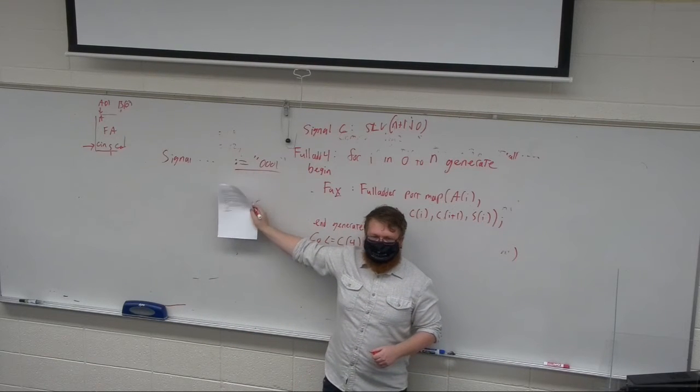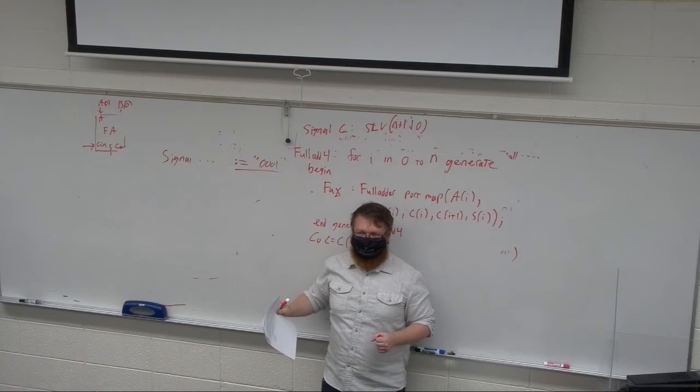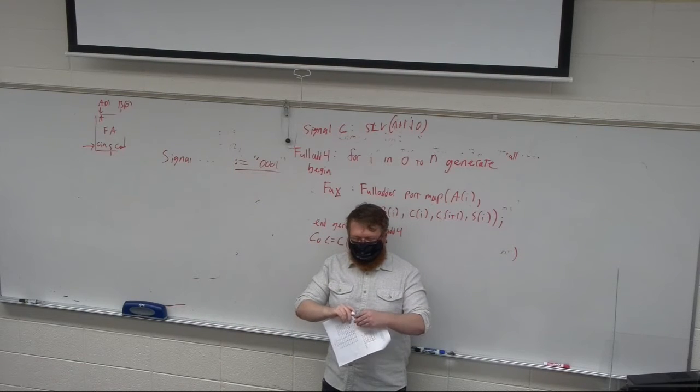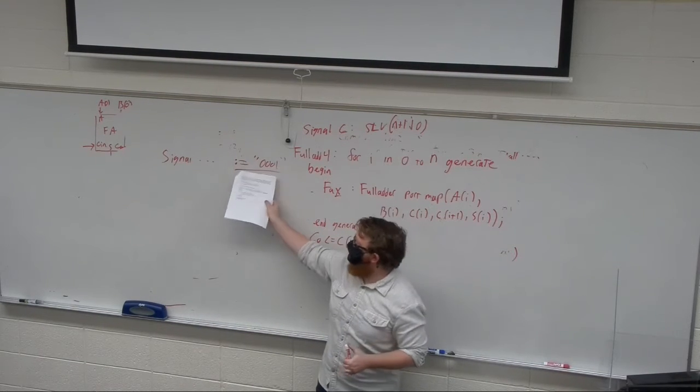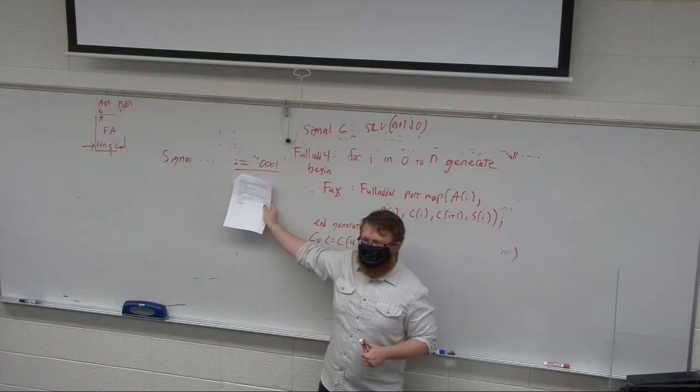Now, I say don't ever rely on this because you don't know what's going to happen. I've done some tests with our FPGAs, and most of the time this works on our FPGAs, but it actually doesn't work all of the time. And the difference seems to be that on our FPGAs, if you ever change this value inside of a loop, it doesn't work.